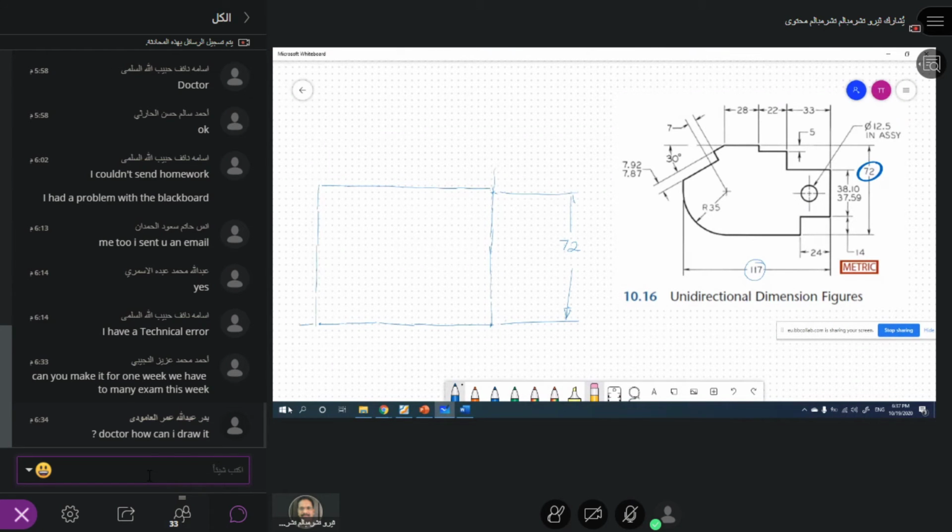And from there, this is the 2H pencil. All right. And from the corner, it is 24 millimeters. So take the corner, measure 24. So this is 24 here. I mark a point here. Then from there, it is 14 millimeters. So here I draw 14 millimeters and draw a parallel line. And this line also, I draw another line, so it touches each other.